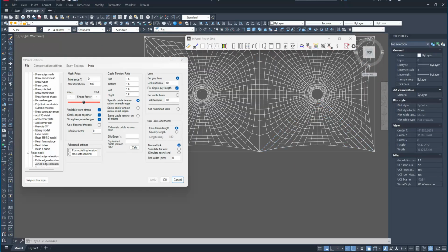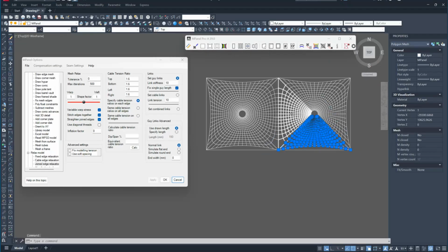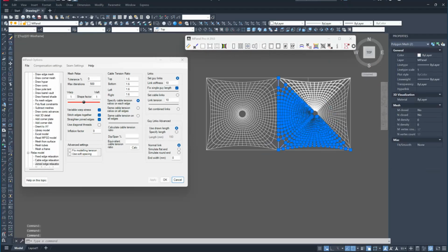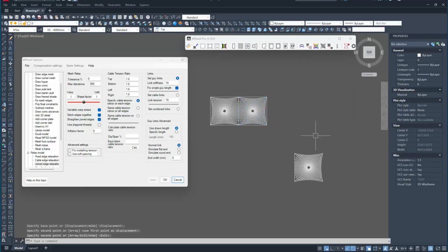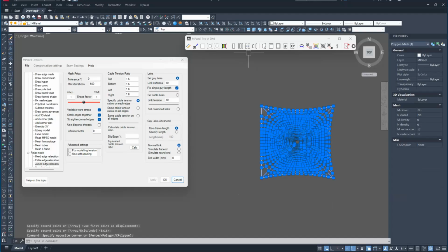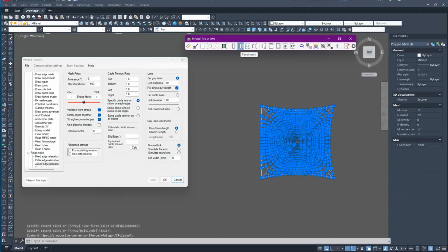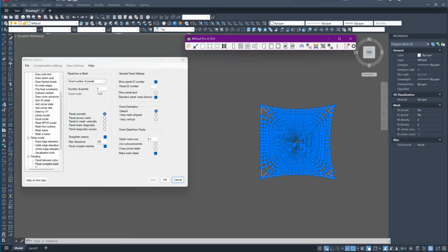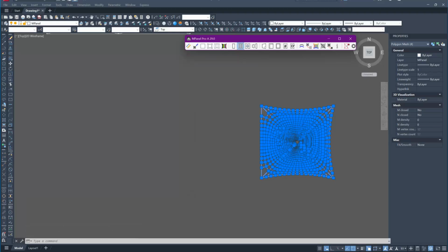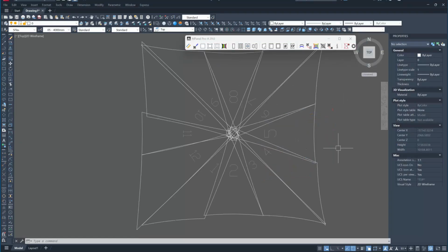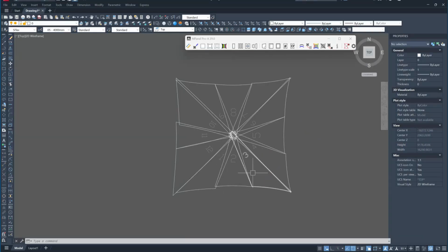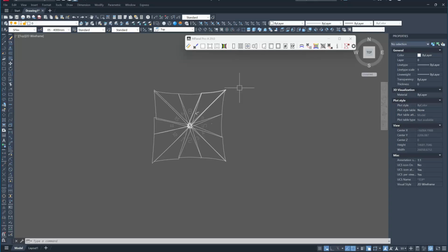So it's now quite possible for us to take a complete set of meshes, make a copy, and use the very simple tool panel a complete mesh. And here I've got it set to number of panels 3, and there we've instantly created all of the panels in a single function. We then proceed normally with compensation, seam allowances, panel stamping, and the output function.